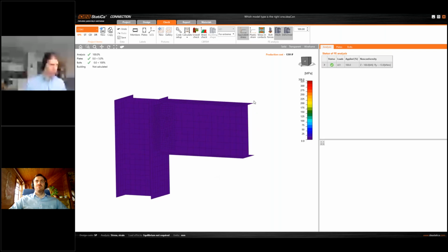And it's because I restricted the shear in the vertical, and I can see that the software is informing me in this non-conformity tab. I can see I have restricted 100 kilonewtons in the Z direction, the vertical, and I have restricted some rotation around the y-axis. So that means bending moment My in the global coordinate system. Where are these forces now?